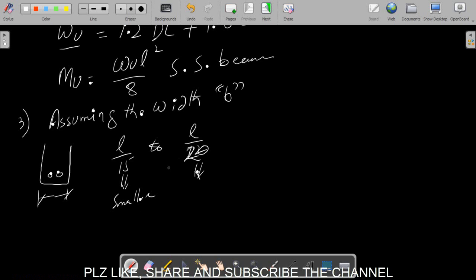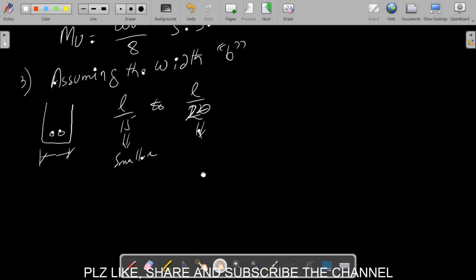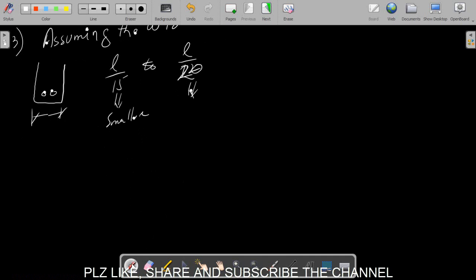After assuming the beam width, remember the beam width must be consistent with the column size or the wall size. This is the important step, right? Let's say we have a beam right here, so the beam width should be such that it can be easily accommodated over the column size.